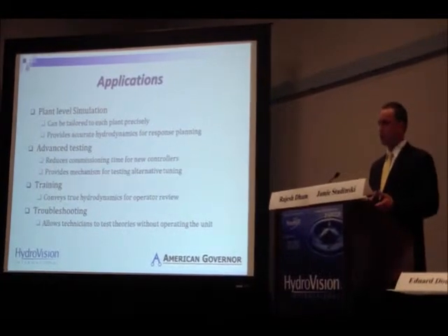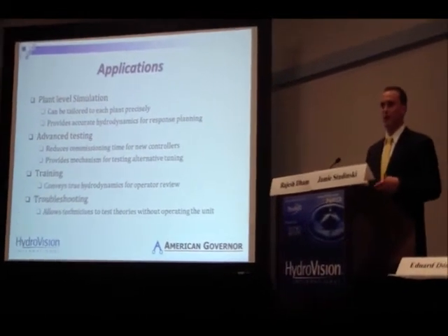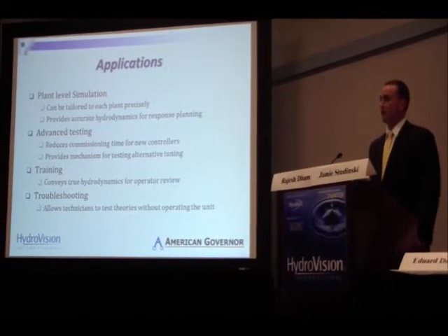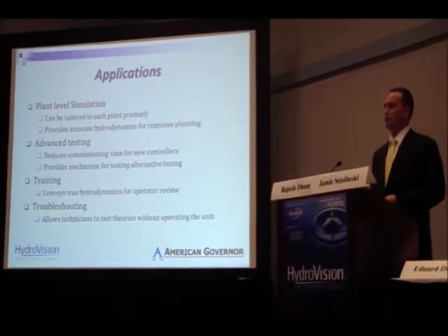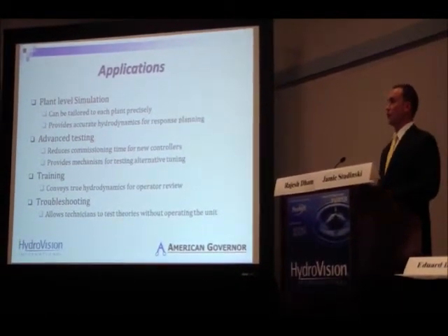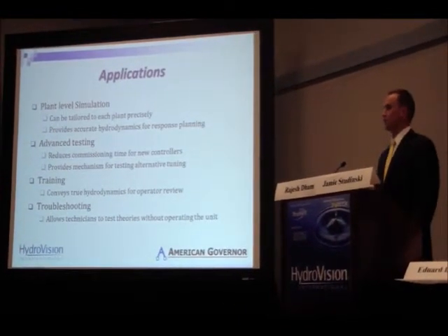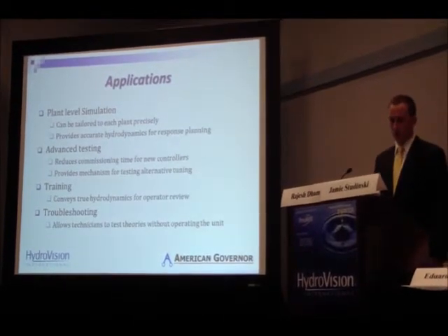So the actual concerns over grid stability can go beyond the unit view itself. And if you're starting to consider how those would affect different plants or how that would affect the grid as a whole, you can actually virtually try to come up with a new scheme. At Grand Coulee, for instance, we use a lead lag controller, not a PID. There are other methods of control algorithms that could be tested in any given scenario, so it gives you some advanced planning capabilities.